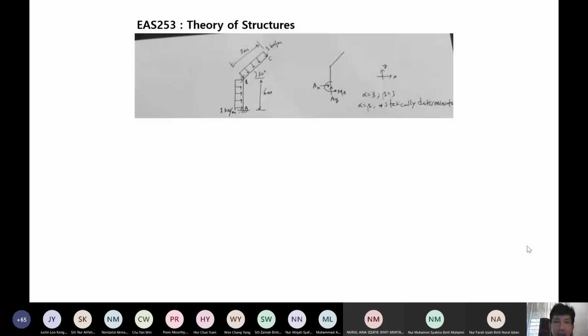So when we take equilibrium of forces in x directions, we find that the only force which is acting in x direction is Dx here. And there is this loading here all acting vertically. So we find Dx is equal to 0.